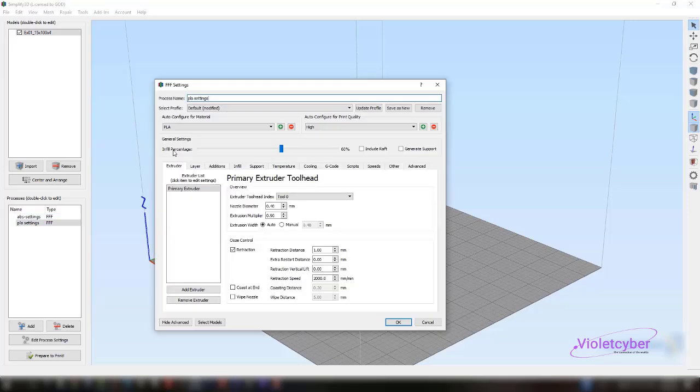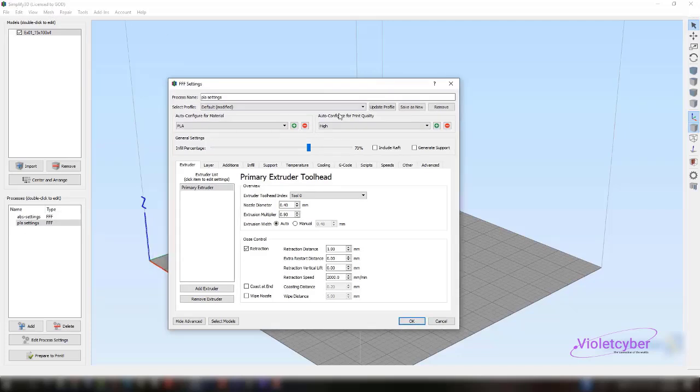Here, for example, I can choose the density of the part, up to 100%. The denser the part, the higher the quality and strength, but the printer uses more material. The less dense, the lower the quality, and the printer uses less material. Depending on that, you can choose the appropriate quality, which is an experimental matter, and you really have to experiment. We have nothing to do with the other settings here; we just want to talk about the body-building tools for robotics, so you can do the work.